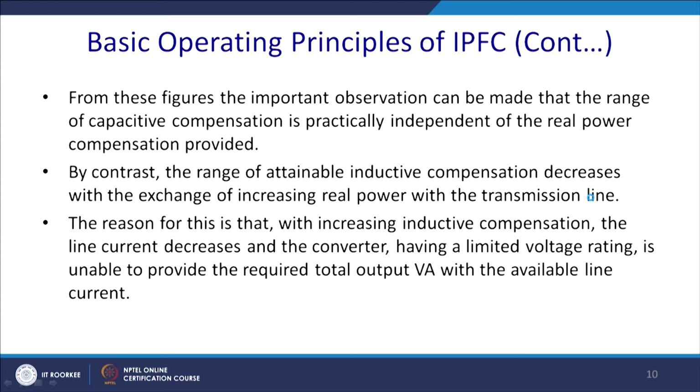By contrast, the range of the attainable inductive compensation decreases with the increase of the real power exchange with the compensation line. So, this is one of the disadvantages. It can compensate capacitive VAR quite well, but since the length of the chord decreases, since you are exchanging the real power, the inductive capability will be reduced, but generally loads are inductive. So, this puts the IPFC in a very dominant position among our FACTS devices. For this reason,